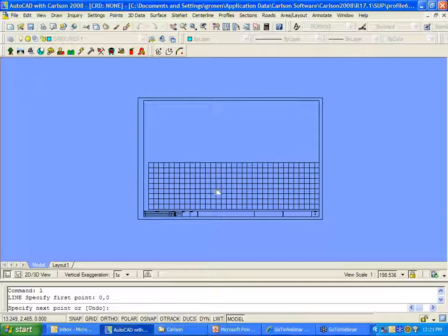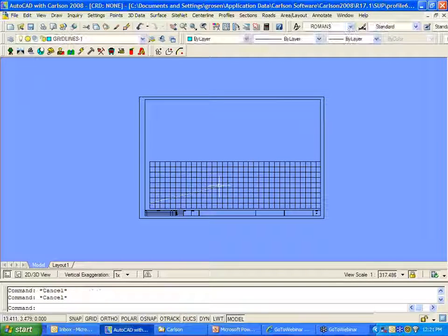So this is the key, or I don't want to use the word trick, but this is the key. If you're setting up your own sheet, of course you can start with one of ours, or you could basically just go in there with one of yours. And the whole thing is, construct it however you want it to look. Maybe your title bar is over on the right side. You have different margins. Obviously, everybody's going to have their own with their logos and all that good stuff. Just remember the importance of 0, 0 on that particular DWG and how it ties into the rest of what's going on. Okay, so I'm going to go ahead and close this.